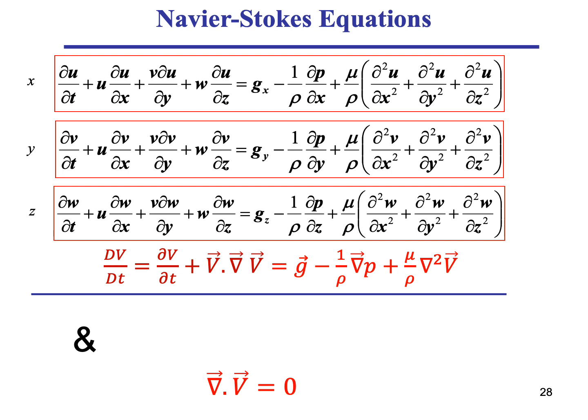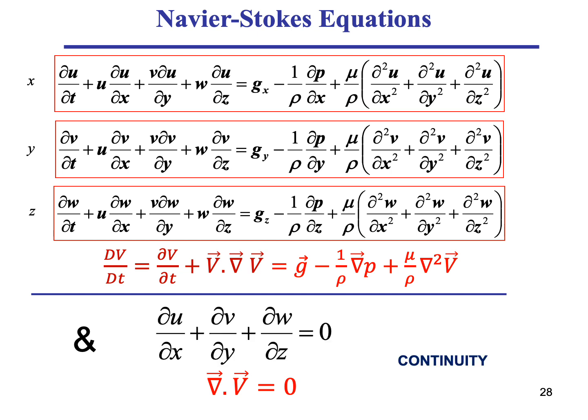If you go back now to the first slide we started with, we have actually derived the Navier-Stokes equation from basic principles. We derived the Navier-Stokes equation and we derived the continuity equation. Let me say a few words here. We'll come back and expand on those later on. If we look at the units, here I have velocity over time, and velocity over time gives me an acceleration, so it's meter per second squared. So this is an acceleration.